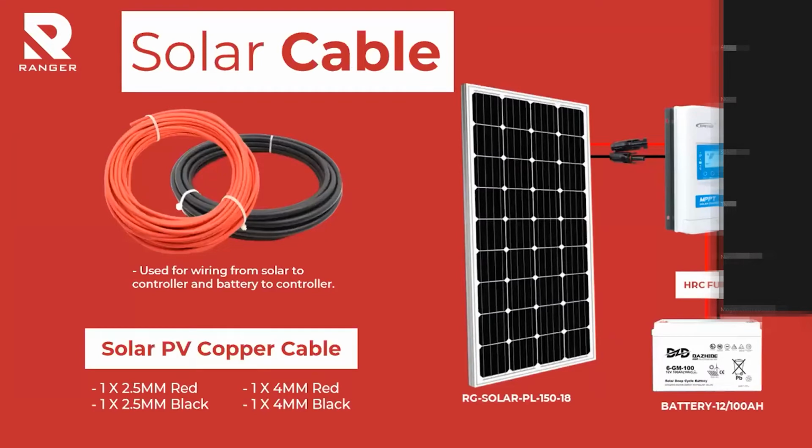Next is the solar cable. As you can see here, solar PV copper cable. This cable is used to connect solar to the controller and battery to the controller. We have two types, which are 2.5 mm and 4 mm, both in red and black color. This figure shows the connection of the solar panel and battery to the solar controller.